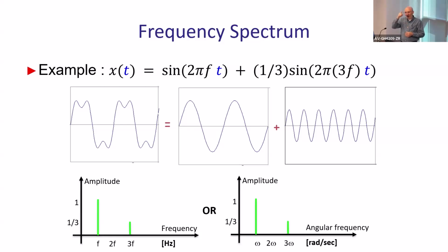Like, do you have a lot of alpha oscillations or beta oscillations? Or maybe you have that 60 Hertz oscillation, which is line noise, which you typically see in all biomedical signals, and you want to remove it. So you'll see some kind of hump around 60 Hertz showing line noise, because these devices record all kinds of line noise and other noises, wherever you record.